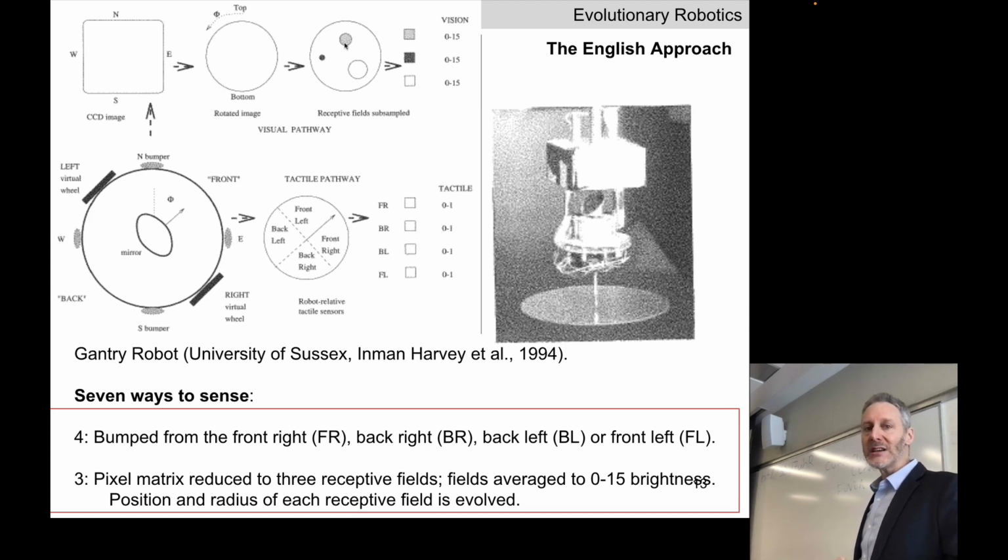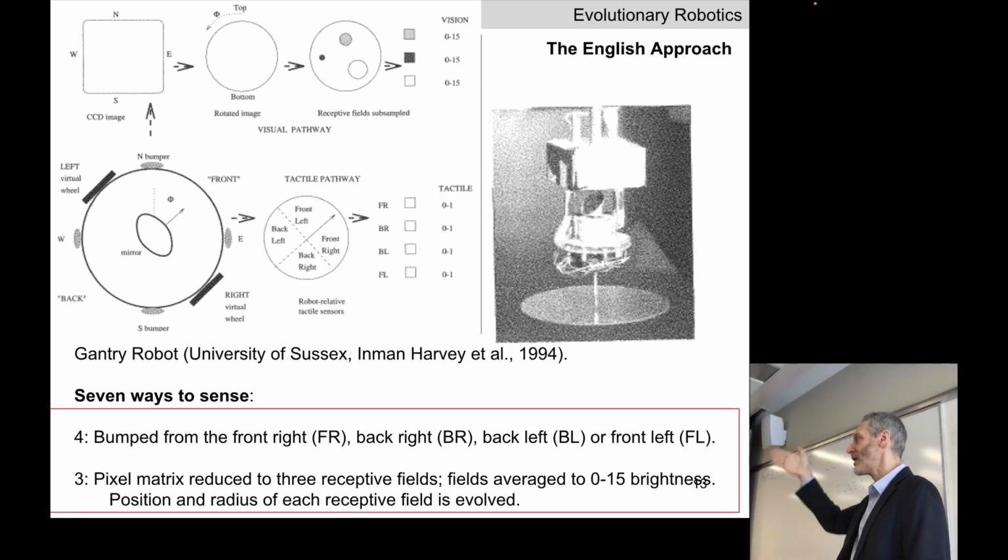In each of these 3 visual fields, at every time step of the experiment, while the physical robot is running, whatever the raw pixel values are inside each of these 3 fovea, they throw away all the color information, keep just the grayscale values, and then average the grayscale values inside that circle.